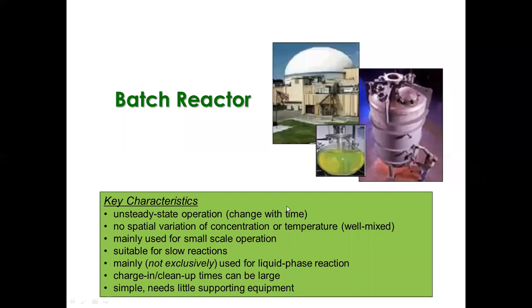Now, however, the main drawback of using the batch reactor is it's mainly used only for small scale operation and is only suitable for slow reactions. So if your reaction is very fast, this reactor is not really suggested. Okay. Now, mainly, though not exclusively, used for liquid phase reaction.